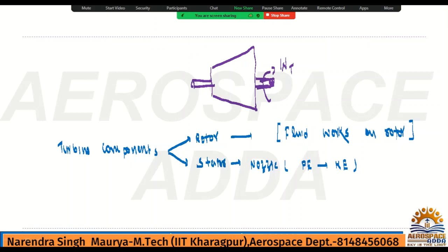So here it is just opposite. Here the fluid, the combustion products, is doing work on the rotor blade, hence it is work producing. There the rotor blades were doing work on the incoming fluid, hence that was absorbing work, and compressor work is negative, and here turbine work is positive.